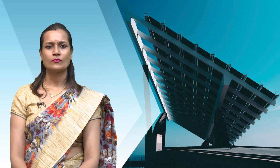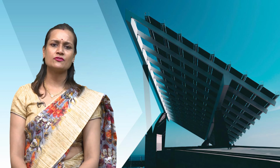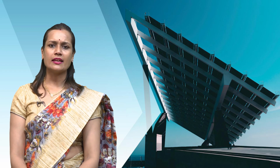Concentrating collectors use mirrors or lenses to focus sunlight onto a smaller area, thus increasing the temperature of the collected heat. A heat transfer fluid such as water, oil or a specialized heat transfer fluid is circulated through the solar collectors. It absorbs the heat from the sunlight and carries it to a heat exchanger or storage system.